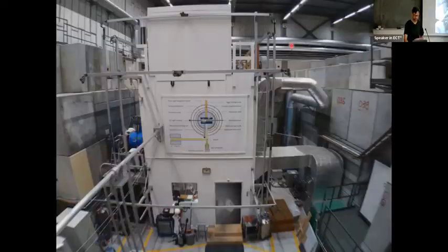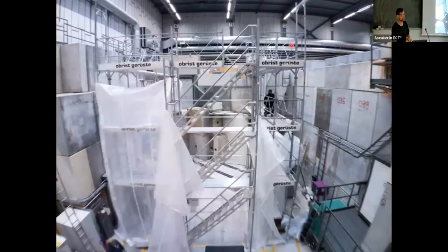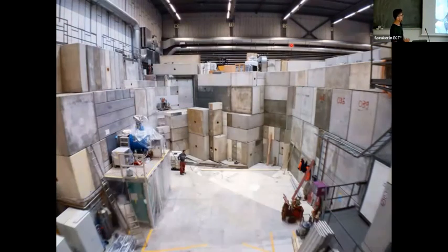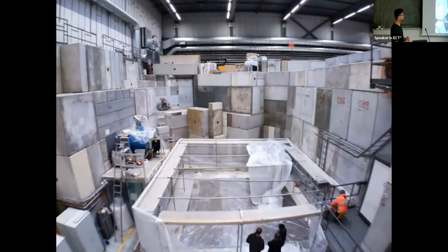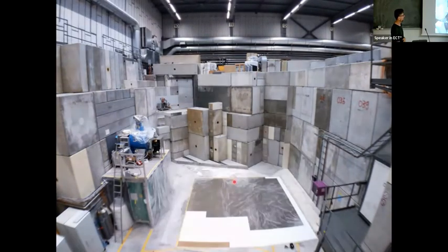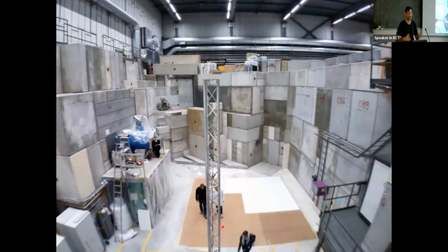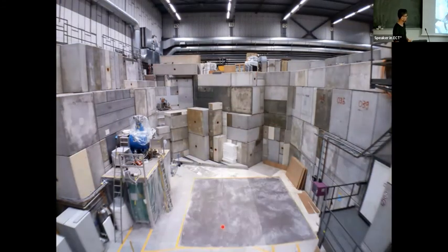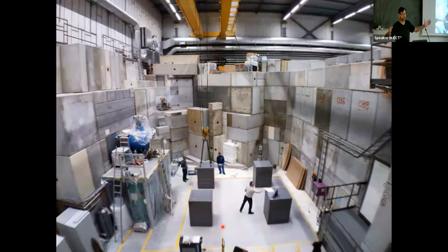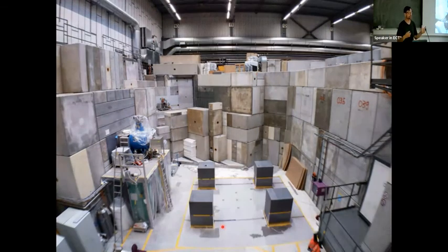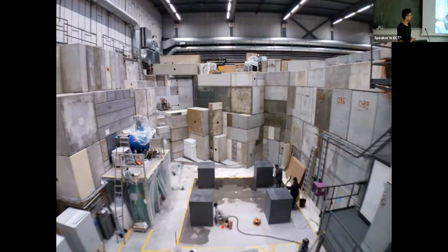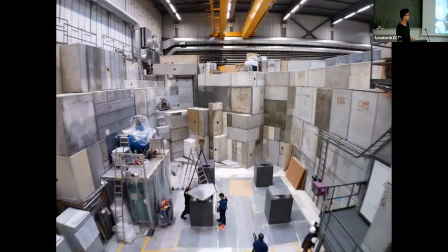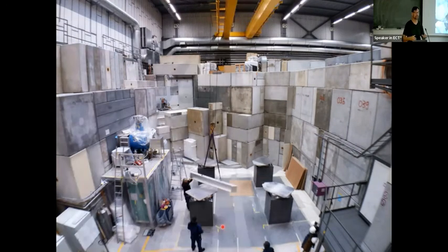And that happened between 2017 and 2020, and you can follow up in the movie. All experimenters already gone. We had to do then some groundwork. So there's a new basement here, essentially a base plate which was produced, which is isolated from the rest of the building to have reduced vibrations. Then we have 4 very nice granite pillars, also to reduce vibrations. And on top of that, we then set up a support for the magnetic shielded room.